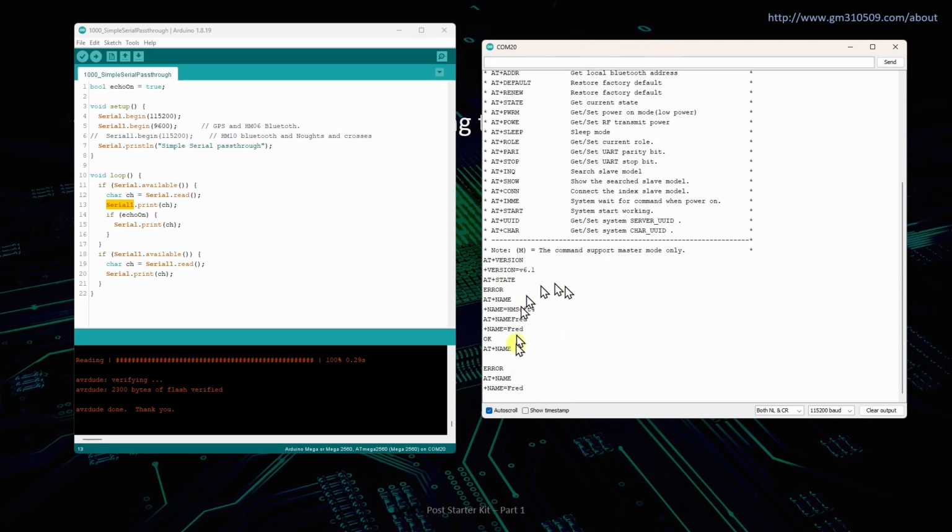So clearly a richer command set is useful, and trying to process 1 character at a time would start to get pretty problematic because, you know, suppose we typed it in incorrectly. So we typed sort of AT plus SL, and then we had to do backspace. If we're processing those characters one at a time, it starts to become problematic to figure out what's going on. It could have meant that we're starting off sleep and gone down to the sleep path, and it's just very complicated. So it's usually better with these sorts of richer command sets to receive a whole line of input, which I'll typically refer to as a sentence, and then process the words or characters in the sentence.